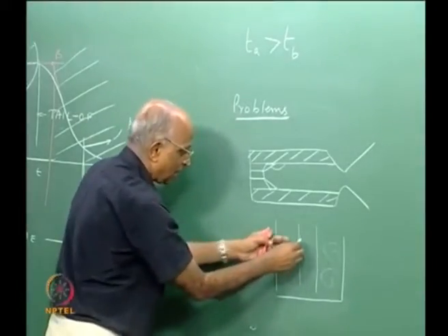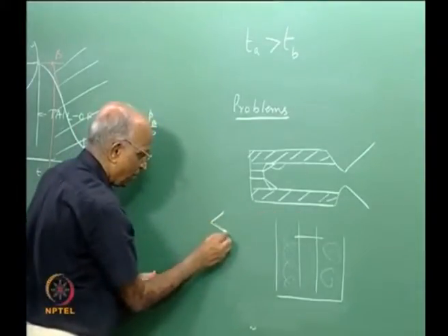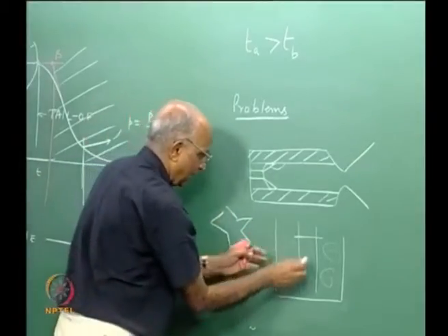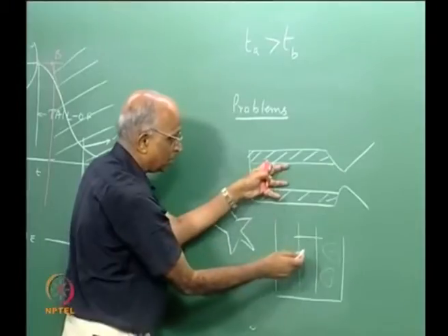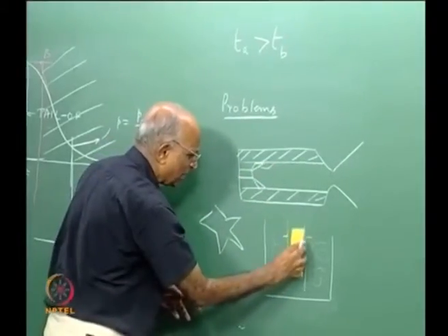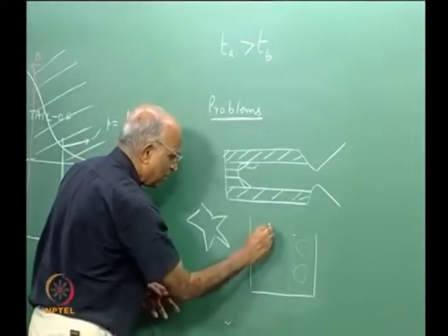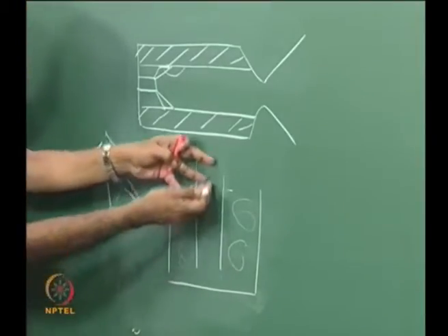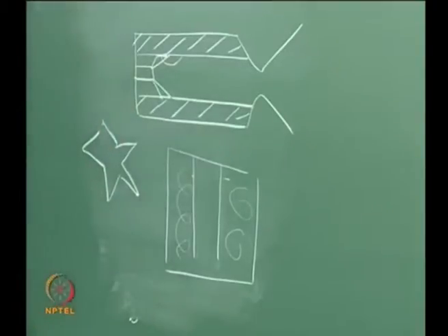If I want to make a star grain, well, the shape of the mandrel which I use should be a star shape, and then I cure it, and then I remove this mandrel, therefore I have this particular shape of the grain over here. On removing, sometimes it is difficult to remove the grain, and therefore we use some agents like silicone oil, which are essentially insulators, to be able to easily remove it, and I form the grain in this particular way.